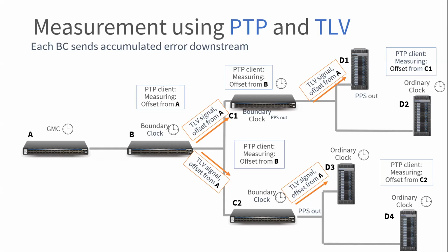But remember that once we signal the TLV, each one of them will know the packet delay variation and the error bound between itself and the superior grandmaster, which can allow us to indicate temperature or packet delay variation problems upstream in the clock tree. Yeah, that's right. So maybe it's not bad.